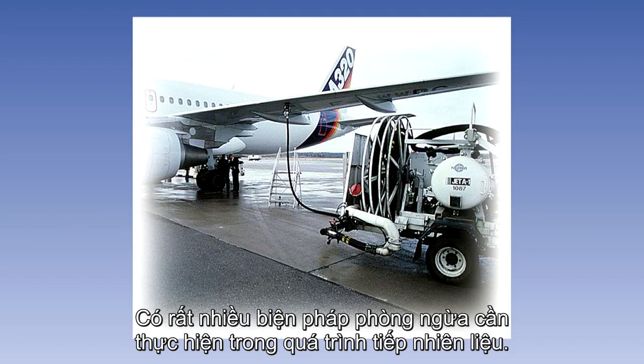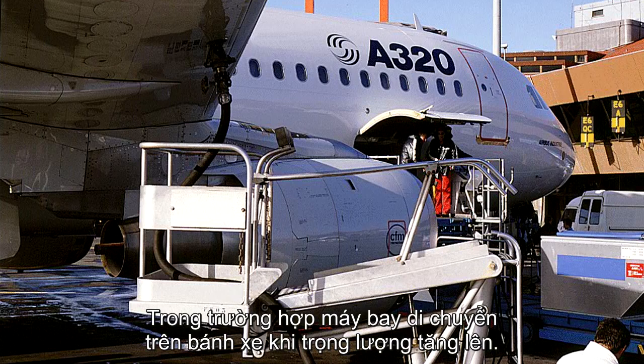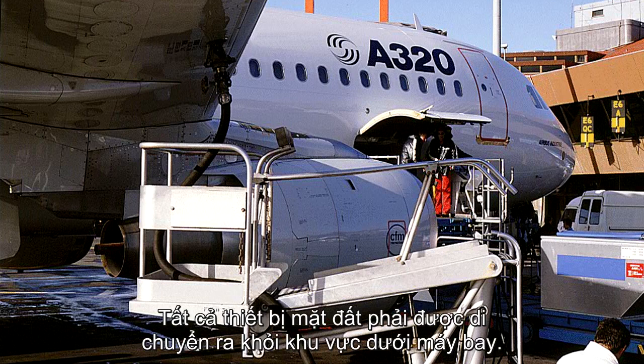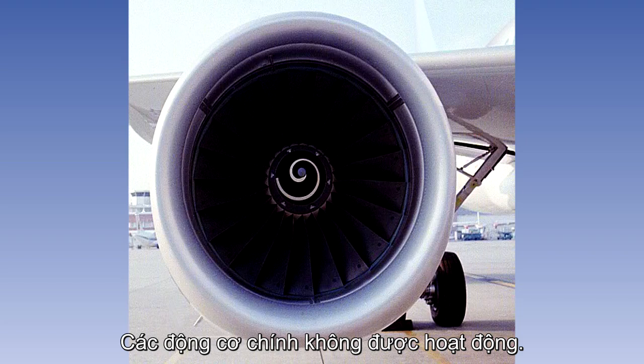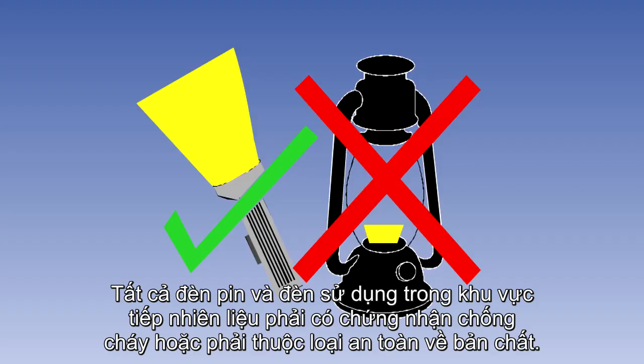There are a large number of precautions which need to be taken during refueling. Here are the precautions that are most relevant to the flight crew. In case the aircraft settles on the landing gear as the weight increases, all ground equipment should be moved clear of the underside of the aircraft. The main engines should not be operated. Strobe lighting should not be used. All torches and lamps used within the refueling zones should be either certified as being flameproof or be of the intrinsically safe type.